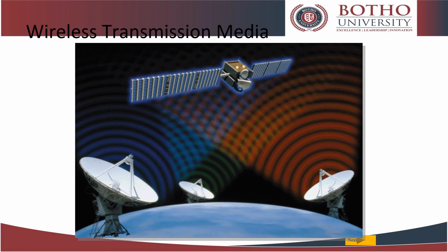Communication satellites are designed to relay several, usually many, signals simultaneously. In some cases, there may be a separate transponder for each carrier. This is typical of broadcasting satellites and of satellites used for distributing television signals to terrestrial broadcasting stations. It comprises a space station that receives microwave signals from an Earth-based station, amplifies the signals, and broadcasts the signals back to any number of Earth-based stations.